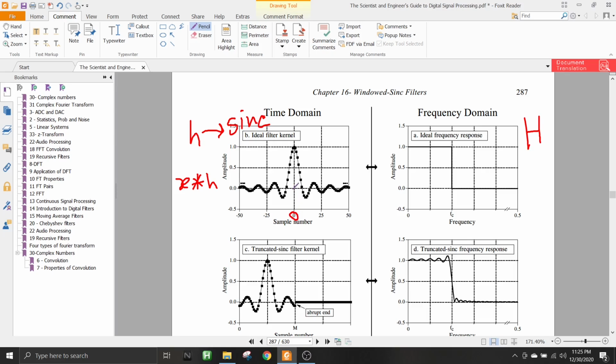So from here, how can we choose 9 samples? We choose 4 samples from the left, 4 samples from the right, and 1 sample from the middle. That's how we get 9. It will always be 1 sample from the middle, then some from the left and some from the right, and how many is determined by M. That means there will be M/2, M/2, then plus 1. This 1 always comes from the central sample.